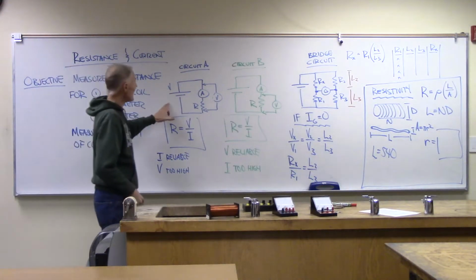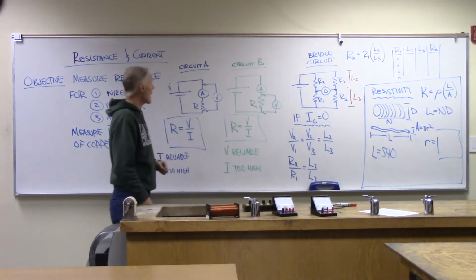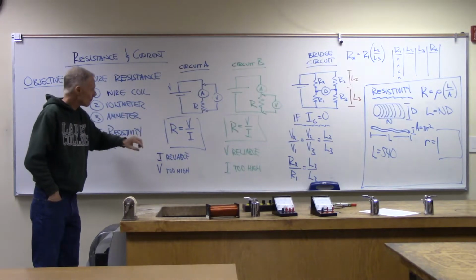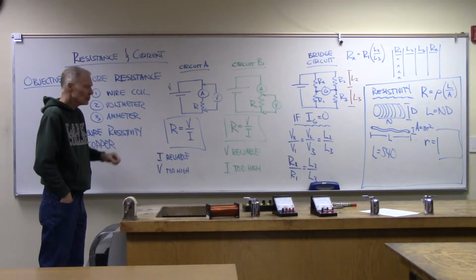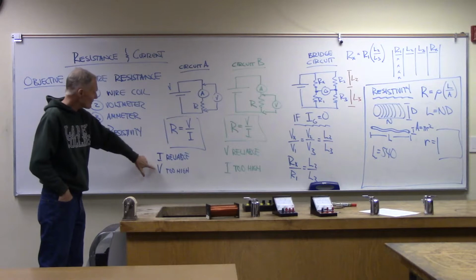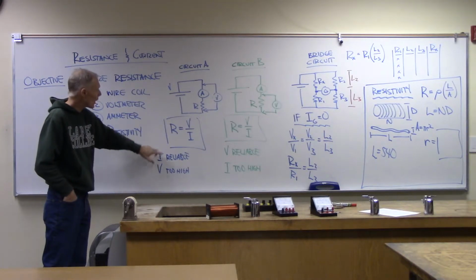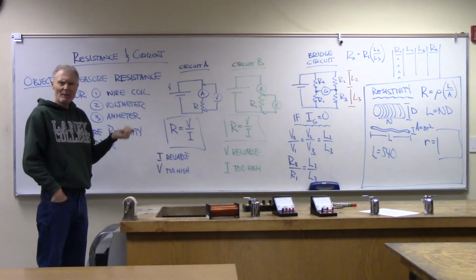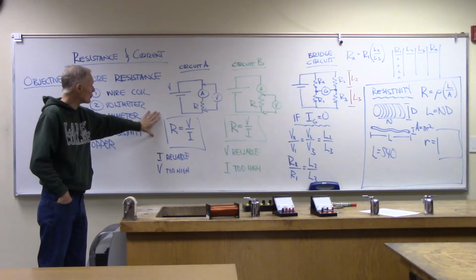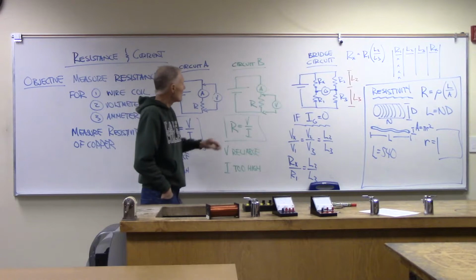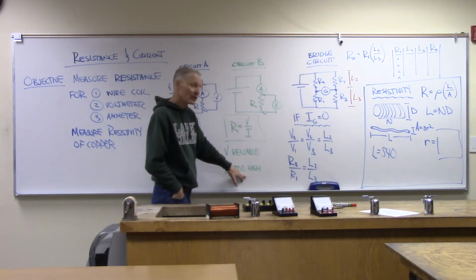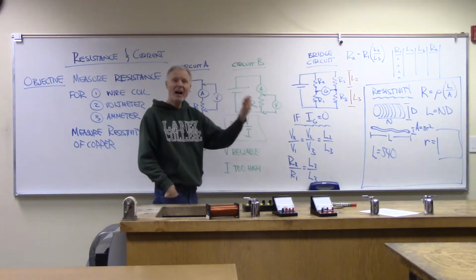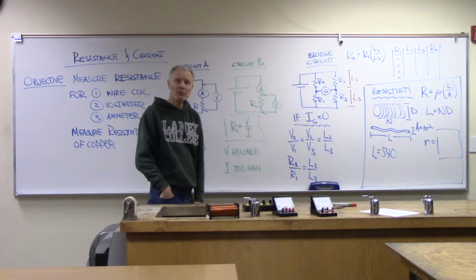So that's what circuit A and circuit B are. Given what we've talked about, we're guessing that since the voltage here is going to be read too high, when I carry out a calculation for the resistance, I'm going to end up with too high of a value using circuit A. If I go to circuit B, it's the current that's going to get measured as being higher, the meter is going to read higher than what the current actually is.